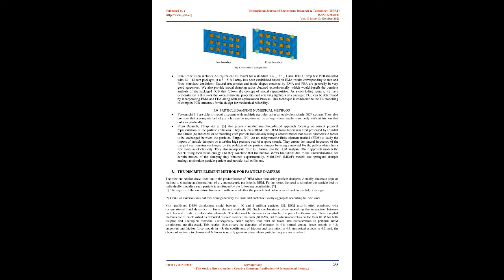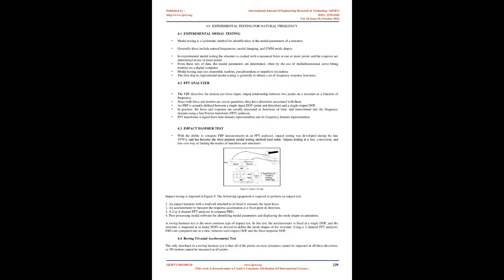Their approach models the pellets using their strain energy and they conclude that the method shows limitations due to the underestimation, for certain modes, of the damping they obtained experimentally. Multi-DOF, MDOF, models use a spring-damper analogy to simulate particle-particle and particle-wall collisions.